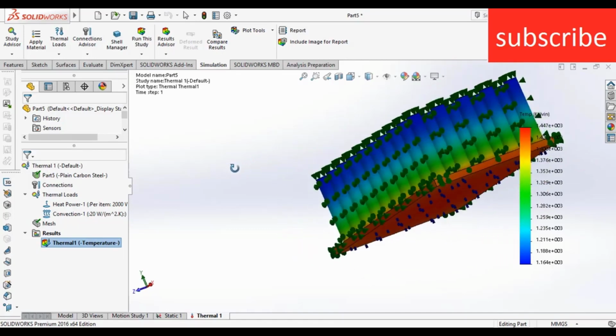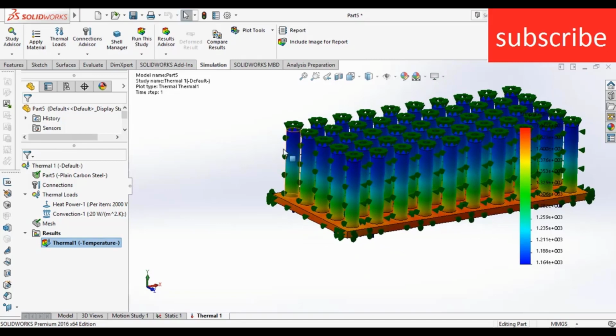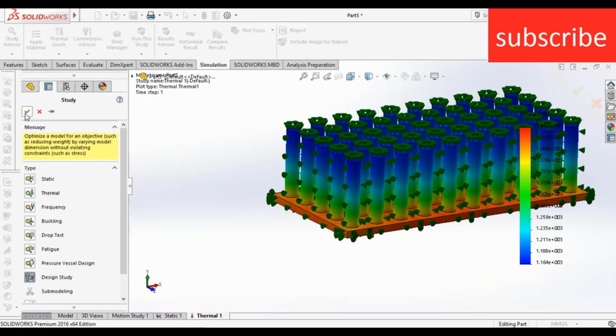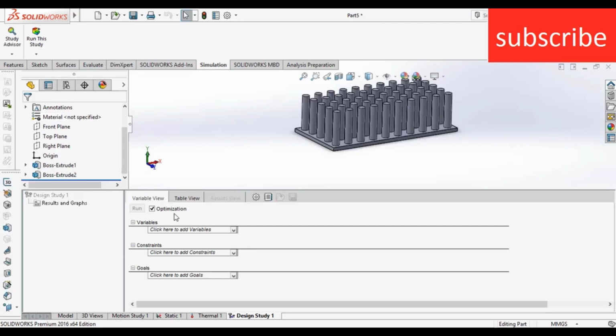Now, to do a design study, first we need to do this simulation. After that, go to study advisor, click on the arrow below, select new study. After that, click on design study, click OK. Now here you can see the word optimization. Basically what I am doing is optimization.